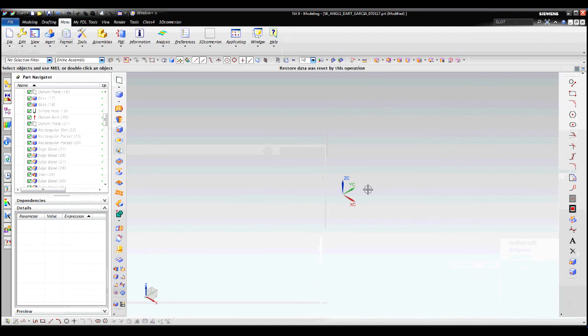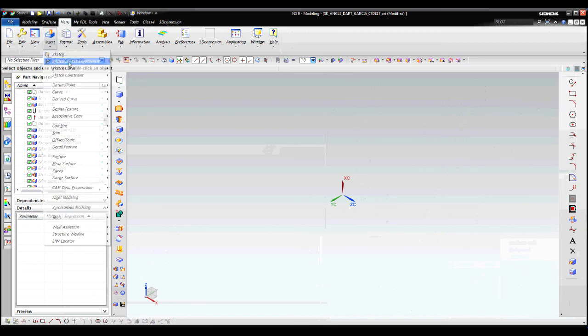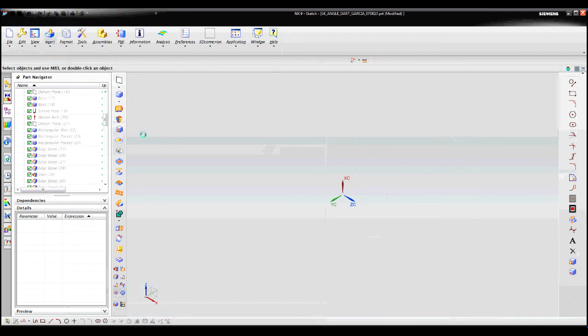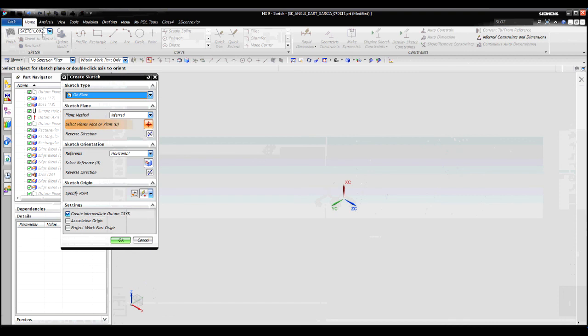We're going to take the WCS, and we're going to position it for the creation of the sketch by just rotating into a working plane. We want the X, Y to be in that direction because that's how we're going to create a profile of the sketch. Go on the Insert, Sketching Task Environment, and we are going to give a name to that sketch, SK underscore.